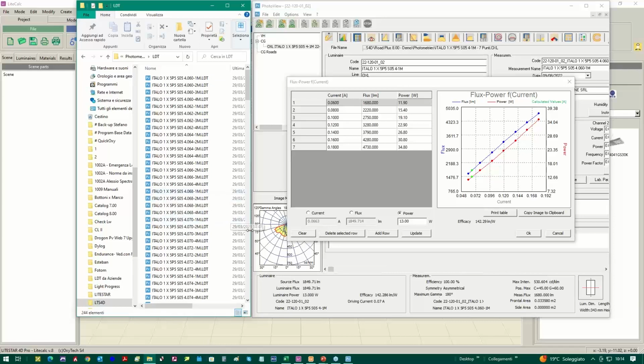But on the other hand, we may input all the different values over here, and the program will automatically create the curve based on a polygonal of segments, as you can see here. This is a method that was described in the brand new standard, IEC 62722-2-1, at Appendix C. And this standard was introduced this year, 2023.